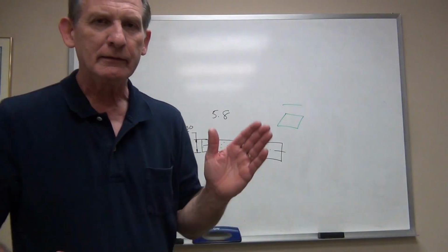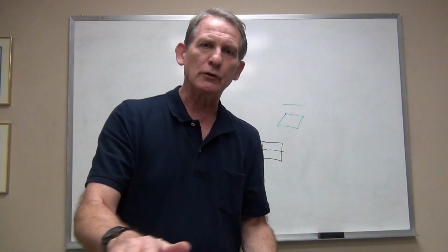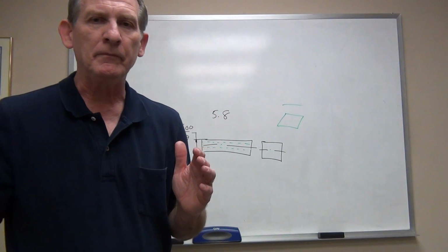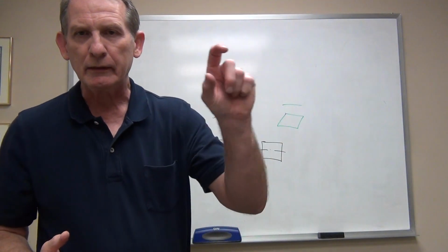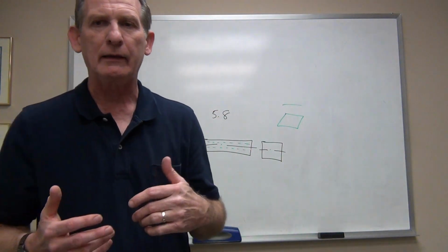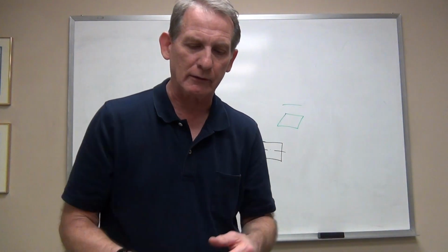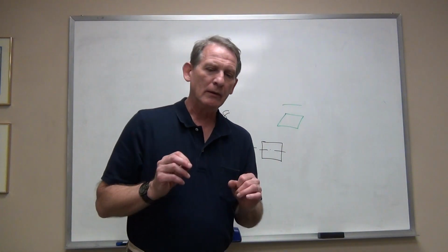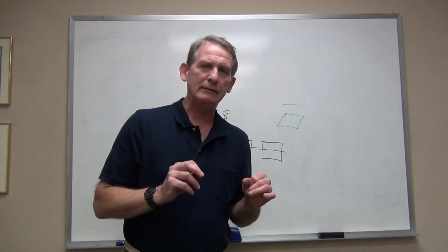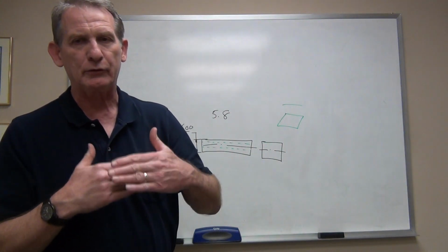If you actually take that bar, even though it's bent, and if you set it on the surface plate, it'll measure 40 thousandths over high limit. It's no longer a flat surface. So if we measure individually down the length of that, we'll see that it is still within size and it is curved. Obviously here in this example, it's curved the most it can be, but we don't violate the size limits in this instance because we are dealing strictly with that derived median element.